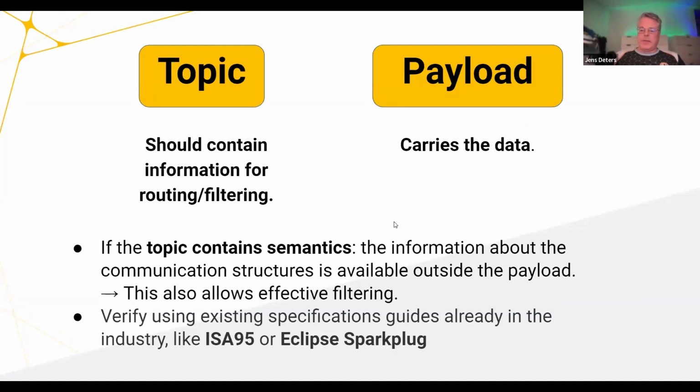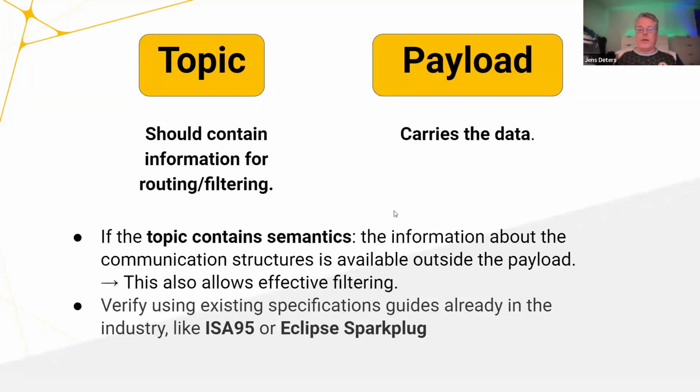The foundation of a unified namespace is actually the MQTT protocol, because it's technically such a great fit for all the requirements that need to be fulfilled in order to create a real-time data hub that reflects everything that's going on in your enterprise at this moment. Using MQTT for implementing a unified namespace leads us to talk about topics and also payloads.